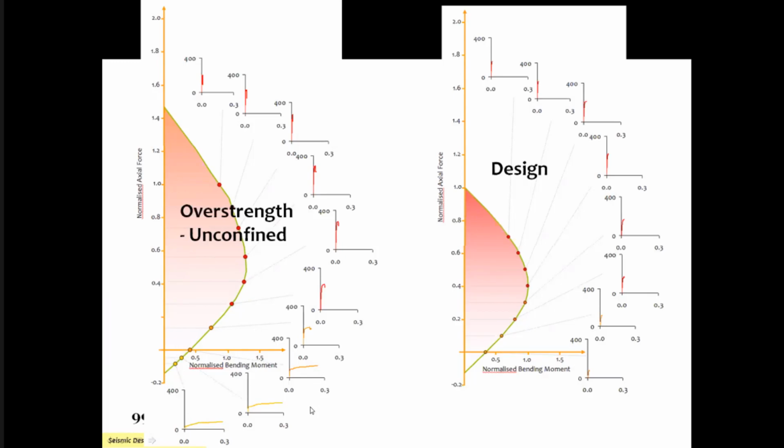And in the lower part, you will see that good ductile actions. But as you come above this point here, there's complete brittle action. Your column will never behave in a ductile way. And so please ensure that you're using larger size column, lower grade of concrete, lower grade of steel as the basis in high seismic regions.